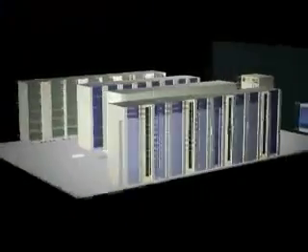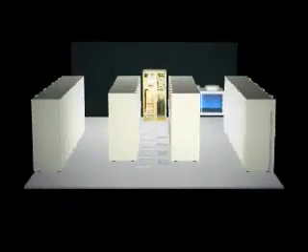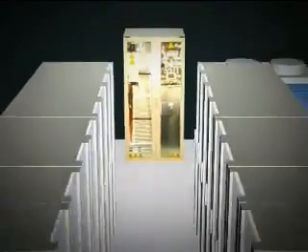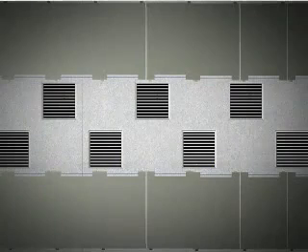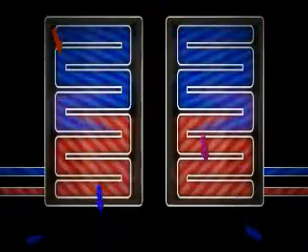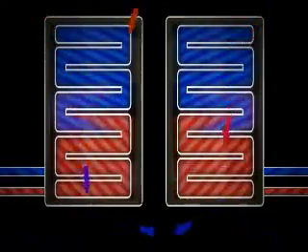Hot aisle, cold aisle systems are a common method of delivering cold air to the servers within a data center. Using computer room air conditioning, generally abbreviated to CRAC, the cold air is pushed under the floor. Using vented tiles, strategically positioned in front of the server enclosures, cold air can escape and be pulled into the server inlets. However, typically, the CRAC system needs to be overrated by 30% to ensure that there's enough air available. Also, running N+1 dual systems again reduces the system's overall efficiency.